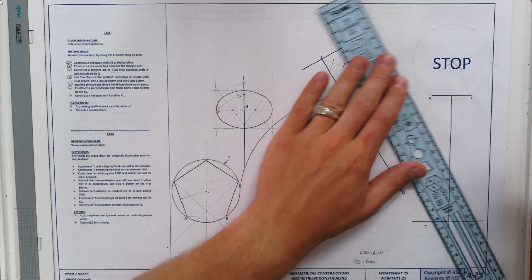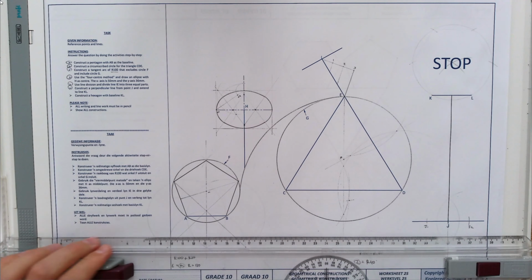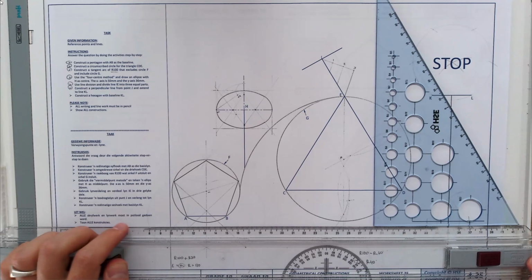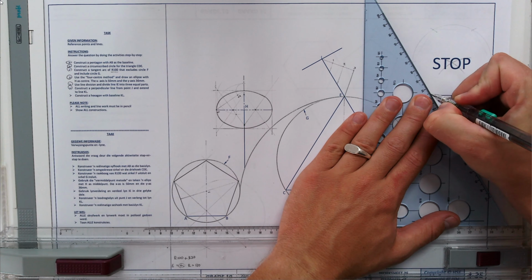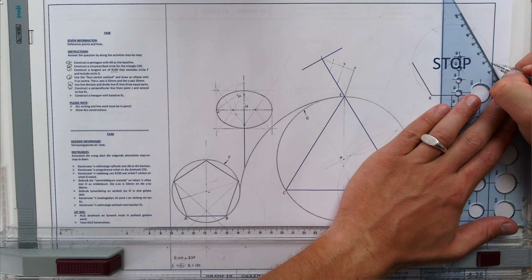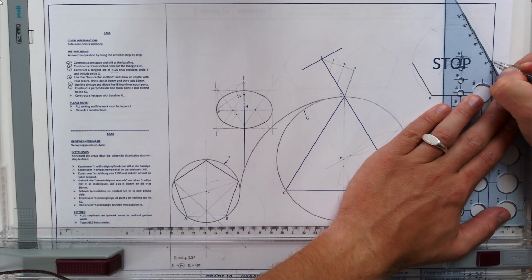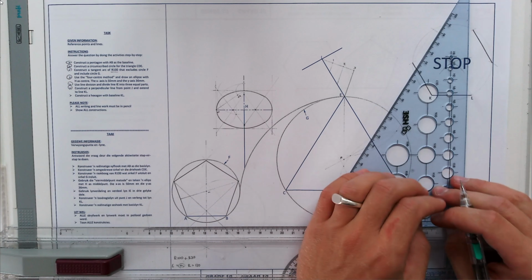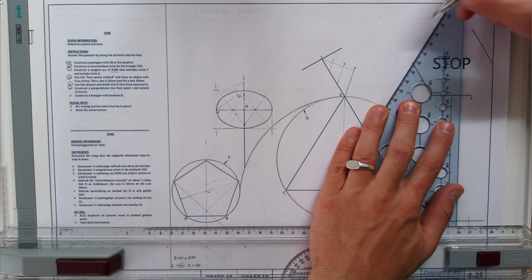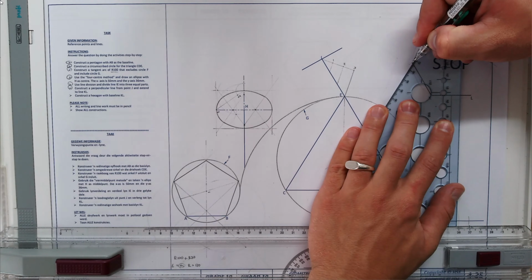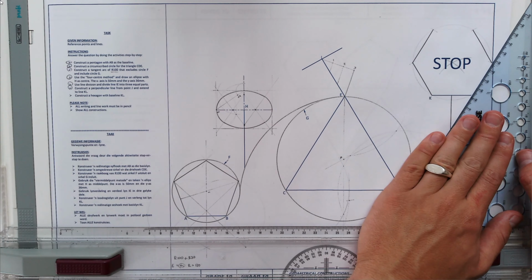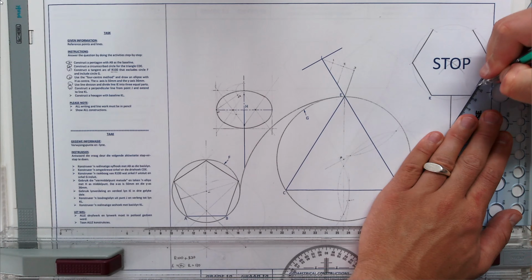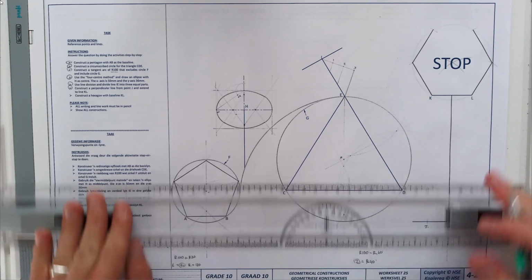You can do it by just using your ruler, or if you want to check yourself, you can see if you've done this accurately, those sides should lie at 60 degrees. So from there to that point, that should be a 60-degree line. From there to that point, that should also be a 60-degree line. Flip your triangle over. From that point to that point, also 60 degrees. And from this point to that point, also 60 degrees. Then we can just close it at the top.